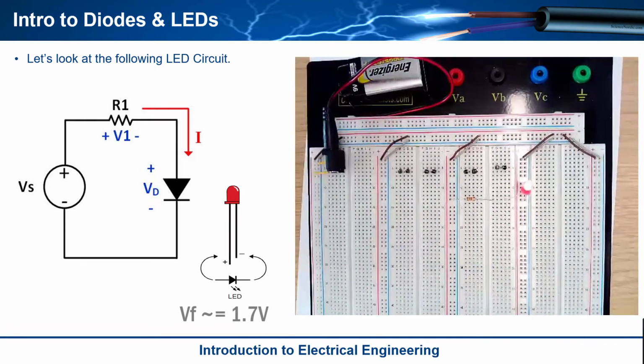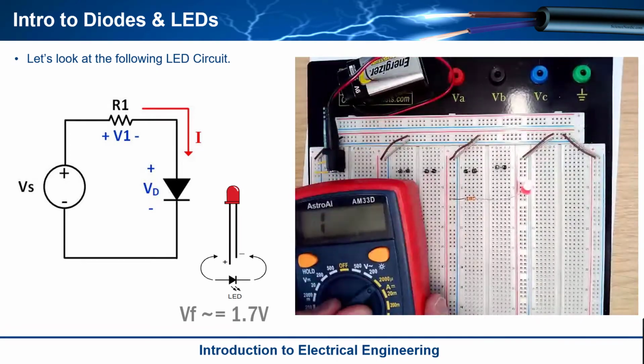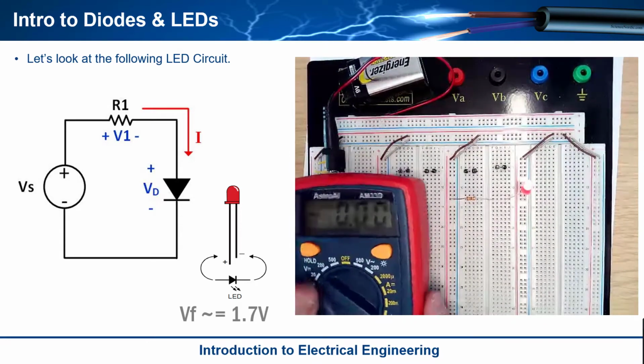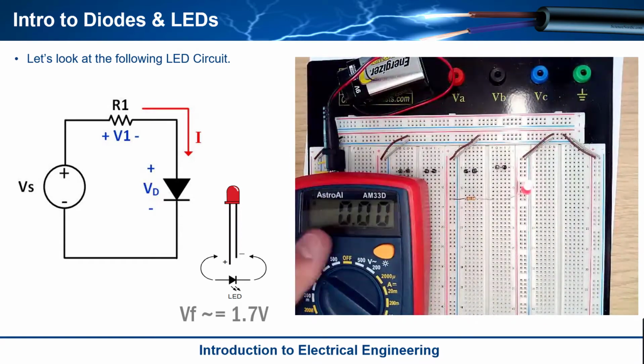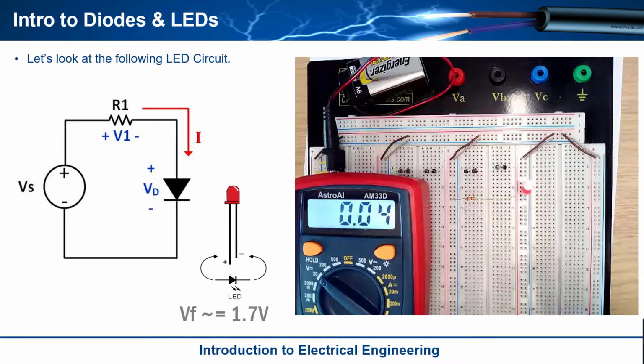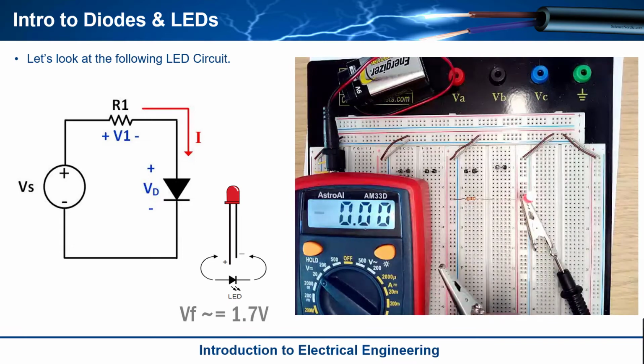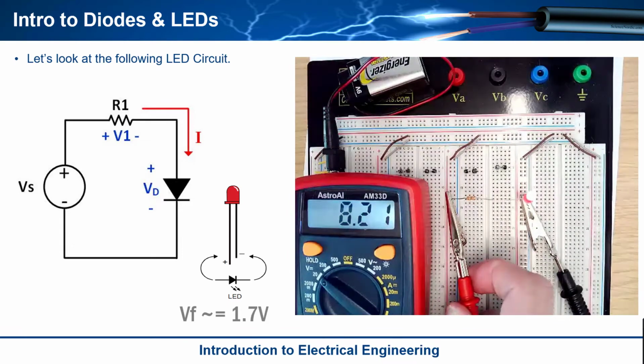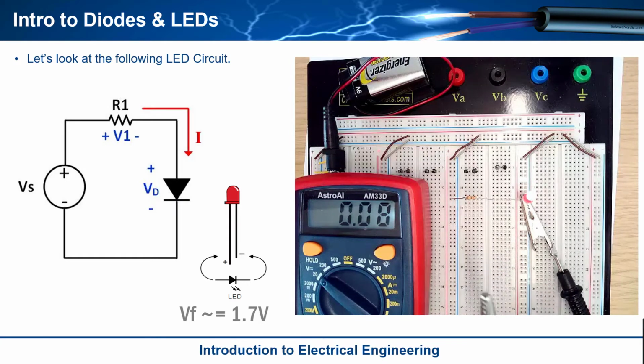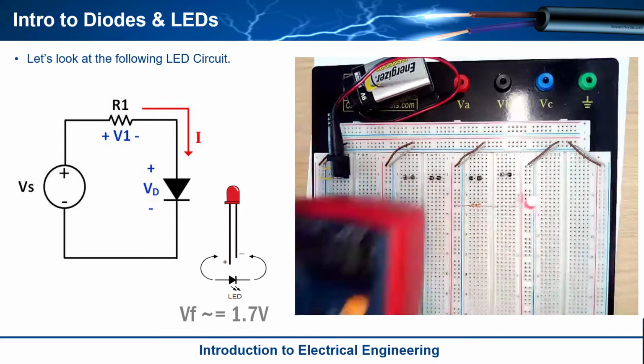Now let's take some measurements and complete our table. So I'm going to come back over here, and the first thing I want to measure is some voltages. So let's go ahead and measure the power supply. The power supply is going to be across the entire series combination of these. So if I touch that, I've got 8.3, holy moly, so that's dropping like crazy. So I got 8.3, and then across the diode I have 1.95. Interesting. Okay, so 8.3 and 1.95.